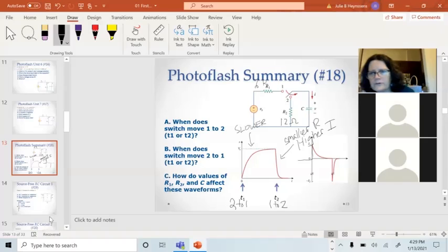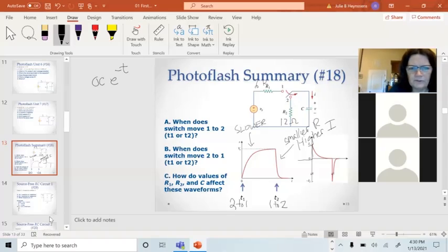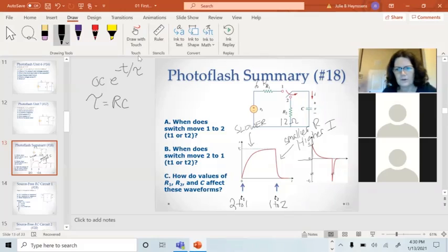Now, people went through and studied this and tried to figure out what was going on. And what they found was the rate of decay. These are both exponential functions, but it's going to be proportional to e to the minus t, t's time, over something called tau. And tau is a time constant. And for these RC circuits, time constant is always RC. That's like an equation I had etched on my eyeballs even when I was a working engineer and didn't use equations. It's how fast things happen.